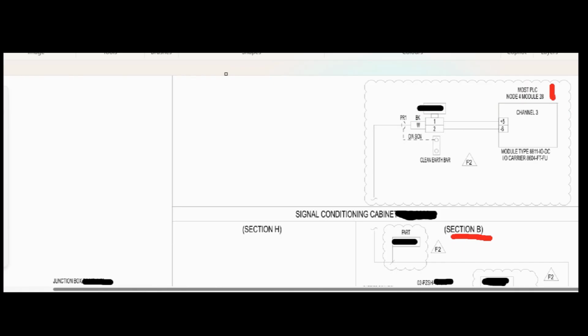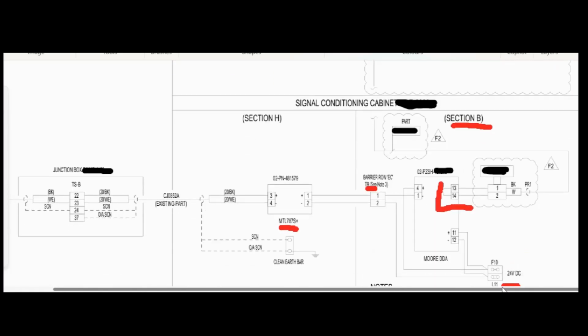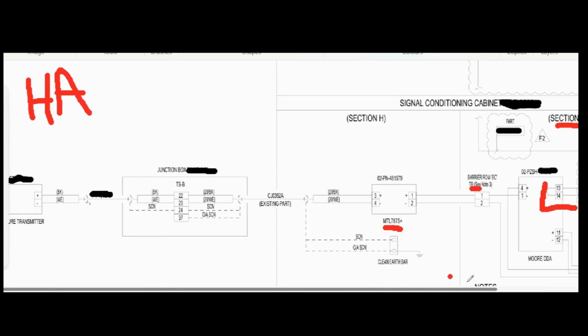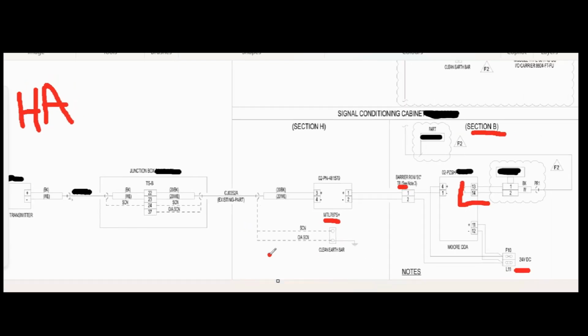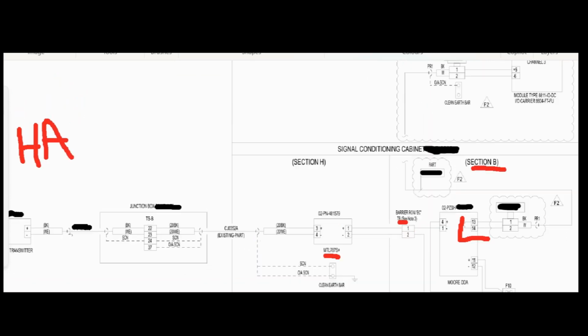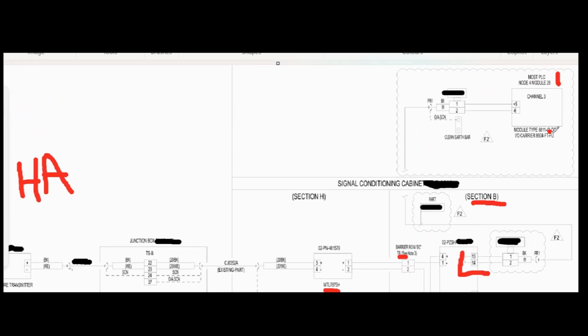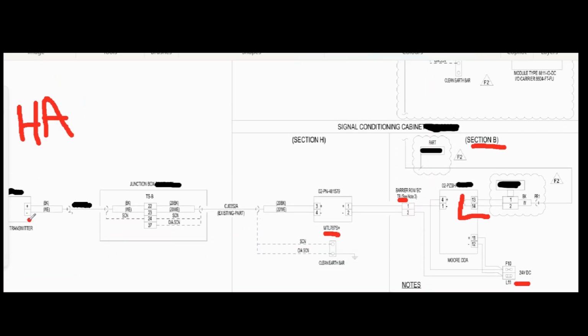So they're basically using an analog pressure transmitter, which gives values in 4 to 20 milliamps, but at the end of it, all you're getting is a digital signal. So they could have really used a switch here at this point. But transmitters are better because it gives you time in the future to change it.